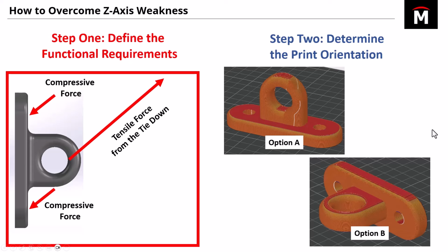And so here's a couple of options that you can see, and you can make your guesses as you want, and we'll actually see how this interacts later on in the experimentation side. But I can say that I wasn't fully confident in either option here for two reasons. The first one is because that tensile force is going to be pretty significant, because at a standstill, maybe it just comes from the bike suspension while it's compressed, but during driving, that force is going to move around and it's going to be amplified by bumps and turns.